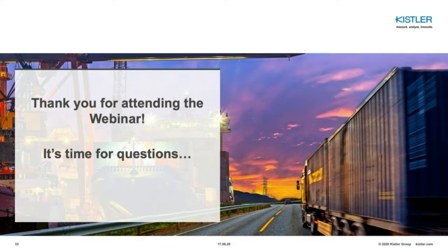I think there's quite a lot of questions received about vehicle classification. And with the KiTraffic Digital, vehicle classification is actually absolutely no problem. We have the information from the force sensors on each axle, so we know axle spacings, we know number of axles. As you've learned, we know even tire types. So vehicle classification based on this information is absolutely no problem. You also learned that we have magnetic field sensors included, so we get magnetic signals, so we know the vehicle dimensions also with the overhangs, and all this information can be taken into account for vehicle classification.